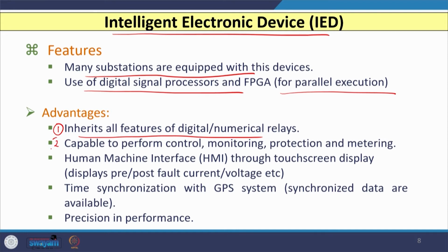The important point for this relay is that it is capable of performing all four functions together, and those functions are control, monitoring, protection and metering. The third advantage of this IED based relay is that it has a human machine interface facility through touchscreen display.